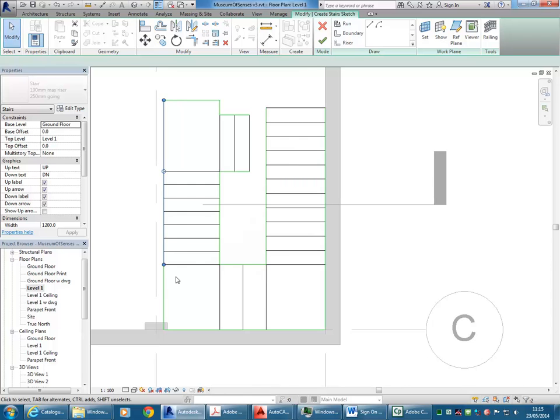It can be tedious. So here I'm just going to make most of the boundaries again. It's usually the boundaries that are going to cause the problems. The risers are a lot more forgiving, actually. You don't even need to have the risers touching the boundaries.